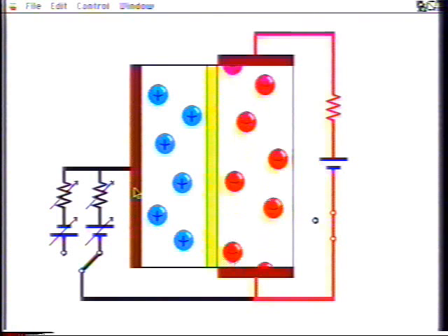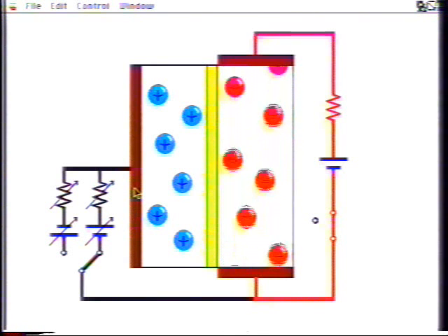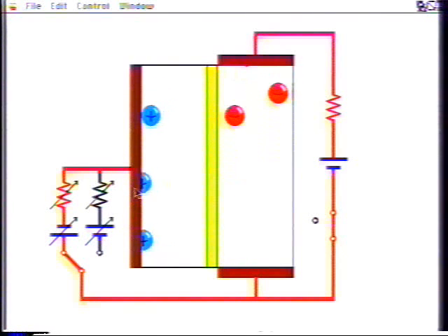The FET switch can be turned off again by withdrawing the positive charge from the gate. Note that transient gate current flows in the reverse direction while the gate capacitance is being discharged, but stops once the discharge is complete.